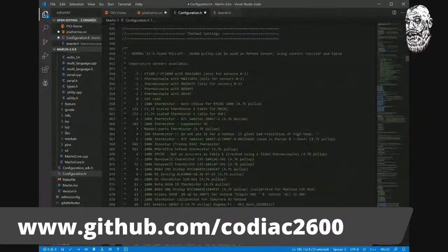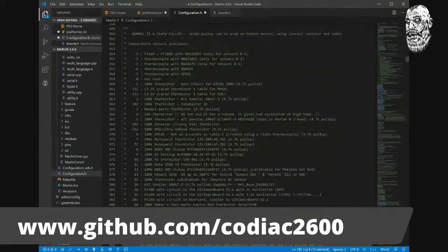So this is interesting. Based on what components you use, again, your components matter. If you have an E3D thermistor, or a Slice thermistor, or some generic glass bead thermistor, this is where this list is important. So 5, right here, is the typical thermistor value that we'd use for an E3D V6 style thermistor, the little copper with the little thing in there.